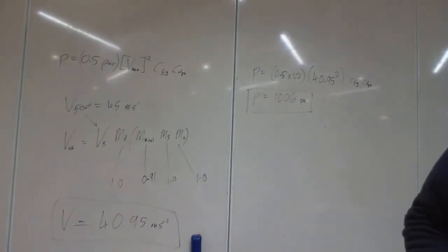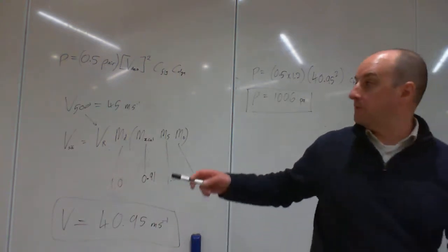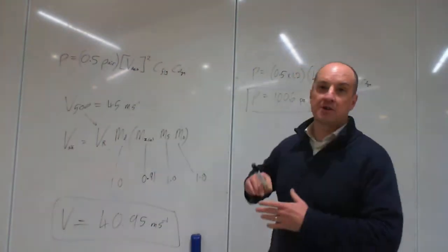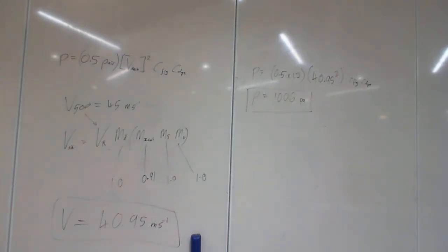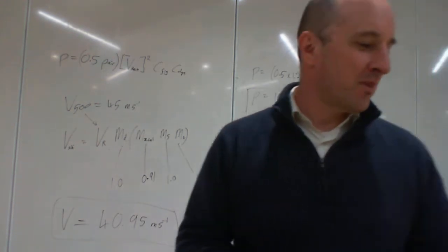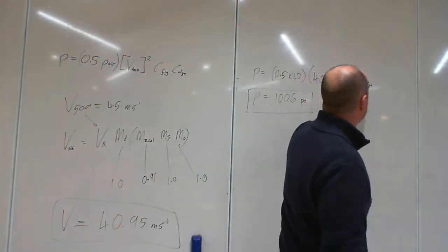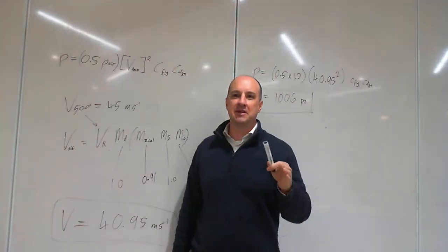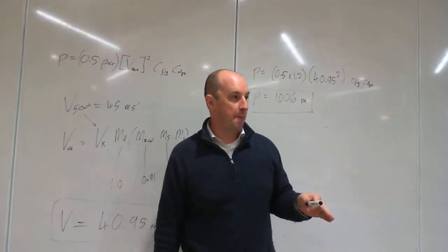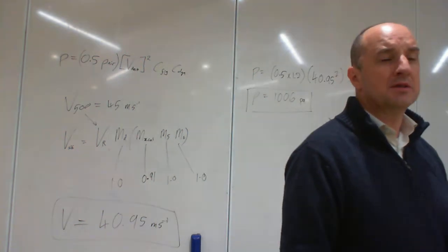That is the first half of the wind speed. Okay, so we found the wind speed. That's the first half of the job done. All right. Now we go to the second half, which is where it starts getting fun. Okay? First, I'll get rid of C dyn. If your structure has a natural frequency of less than 1.2 hertz, I think it's 1.2, maybe it's 1 hertz.